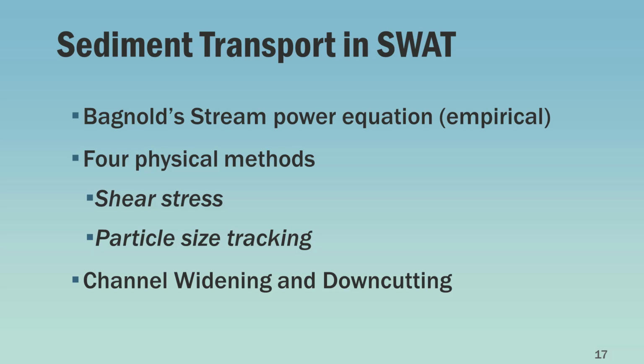Sediment transport in the SWAT model until recently has generally relied on the Bagnold stream power equation with user-defined factors for erosion and channel cover. Sediment transport is simulated generally at the daily time step, but recent developments of the SWAT code have incorporated new physically based methods that incorporate shear stress and particle size tracking. However, these routines have not been thoroughly tested. I can recall one paper that has evaluated these routines and suggests that the new routines do a decent job. SWAT also incorporates a channel widening and downcutting algorithm.